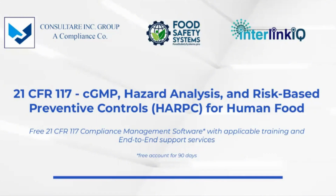Group. Today, we will focus on understanding the structure and key requirements of 21 CFR Part 117, which form the foundation of FDA's food safety regulations for human food. This includes compliance with current good manufacturing practices, or CGMP, under Subpart B and the implementation of hazard analysis and risk-based preventive controls, or HARPC, under Subparts C and G. These requirements are designed to ensure that food is manufactured, processed, packed, and held under sanitary conditions, minimizing risk of contamination and ensuring consumer safety.